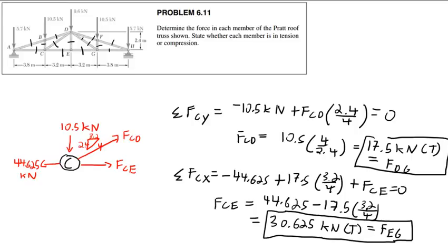Okay, we use the formula that says that m is equal to 2n minus 3. It takes the number of pins, multiplies it by 2, and subtracts 3. That's the number of members. m plus r is less than or equal to 2j is one I'm familiar with. Just using the book formula. So it's got 8 pins, times 2 is 16, minus 3 should be 13 solutions, right? How many solutions are there supposed to be using that formula?